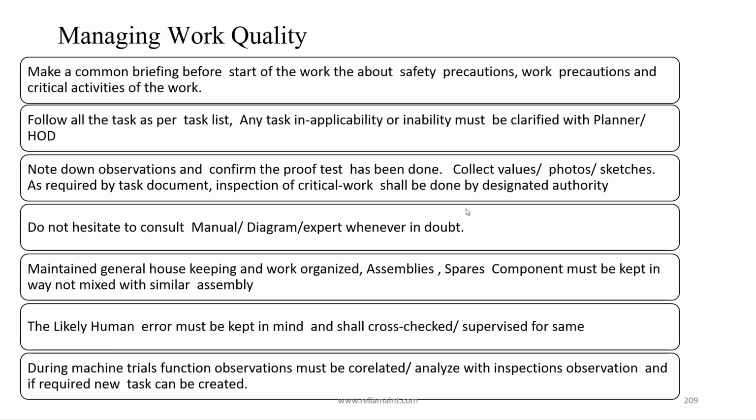Do not hesitate to consult manual/diagram/expert whenever in doubt. Maintain general housekeeping and keep work organized. Assemblies and spare components must be kept in a way not mixed with similar assemblies. The likely human error must be kept in mind and shall be cross-checked/supervised for the same. During machine trials, function observations must be correlated/analyzed with inspection observations, and if required, a new task can be created.